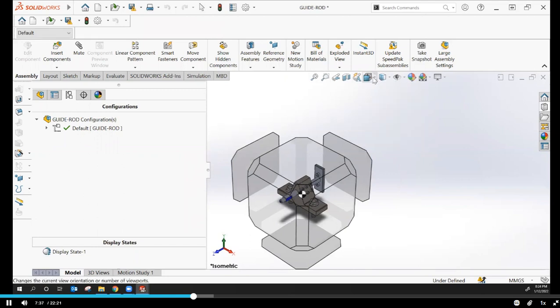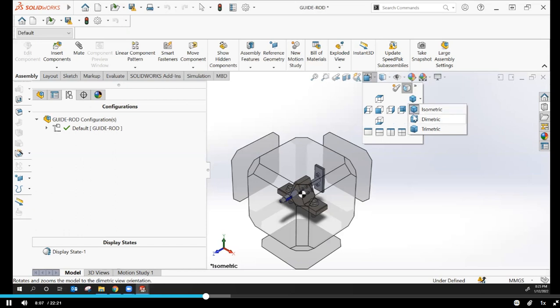Here is the heads up toolbar with this view. These blue indicates the face that you're looking at. So this would be the front view of this isometric cube. This being the top, the left, the bottom, the right, and the back. Over here is a black arrow, which tells us there's something available. We've got isometric, dimetric, and trimetric. Isometric is at the 30, 60, 90 angle, which we're shown here. Depending on how you're displaying it and what it is you want to show, you may use these other features as well. I commonly will use isometric.